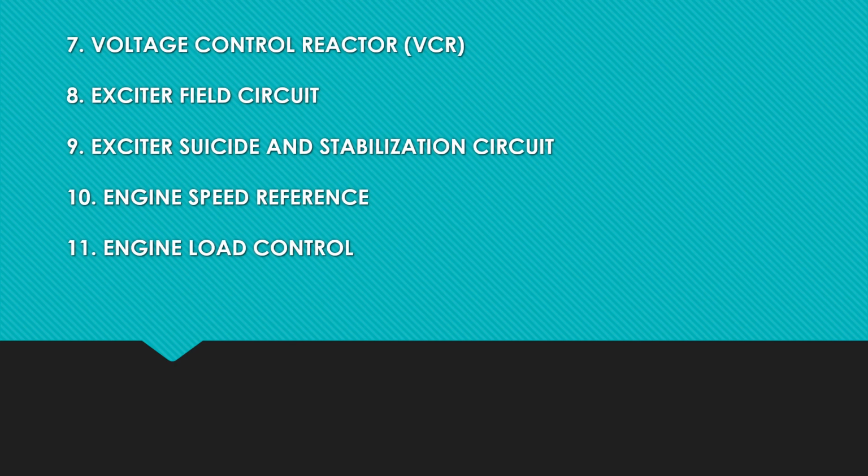Next we have engine load control. Governor load control potentiometer or LCP is connected in the circuit through LCR1 and LCR2 resistors. The potentiometer LCP is normally held at minimum during normal working of engine. In case of excess load on engine, LCP moves and a higher voltage appears at wire 29A passing current through PWM winding, reducing the excitation.